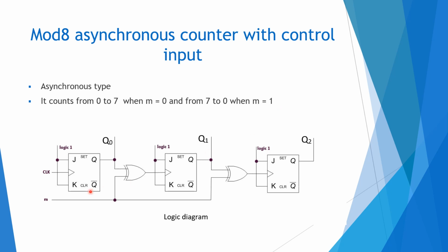So here we have designed it. Here you can see the logic behind the up and down counters. For an up counter, the Q of the first flip flop is connected to the clock of the other.